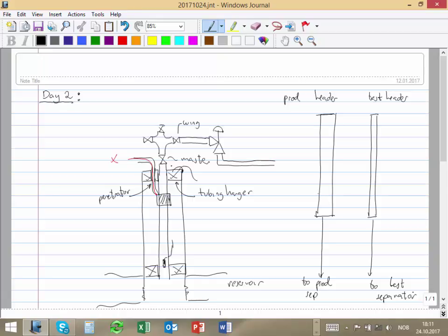It is by law, you have to report it, and the only allowed method to measure is using a test separator, nothing else. No matter if you come and you're a genius and say I found a method that gives you 100% accuracy, it is the same, they don't accept it. They say you have to have 2 lines, and that's very costly. For an onshore system, no big deal, you put 2 pipes, that's all. But for an offshore system, it can be extremely expensive.